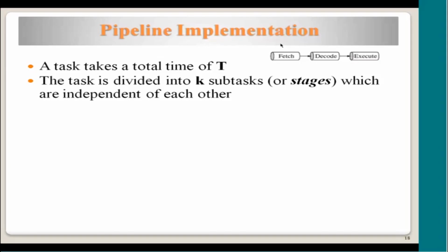Then you divide the operation of the add instruction. So what are the operations involved to perform an add operation? First of all, the add instruction needs to be fetched from memory and decoded, as I showed you with the decode logic inside the processor. Based on the decoding, the relevant registers are accessed, the operation, if it is an add or subtract, is performed during the execution cycle, and the result needs to be written back into the register.